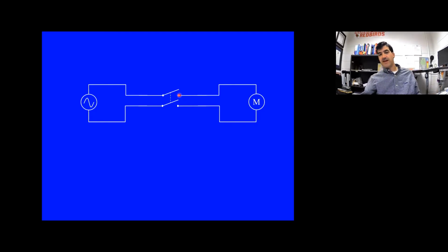So this is kind of a switch that offers a higher degree of safety or redundancy. I mean, this would work just fine with a single pole, single throw switch on one of these wires, either this one or this one. But just in case one of the contacts gets welded shut accidentally or stops working, this is a redundant method of breaking the current through the circuit.